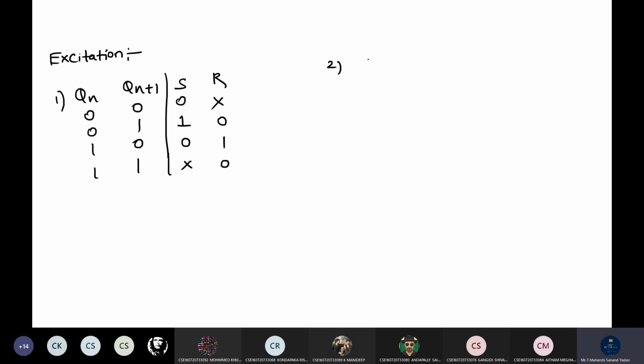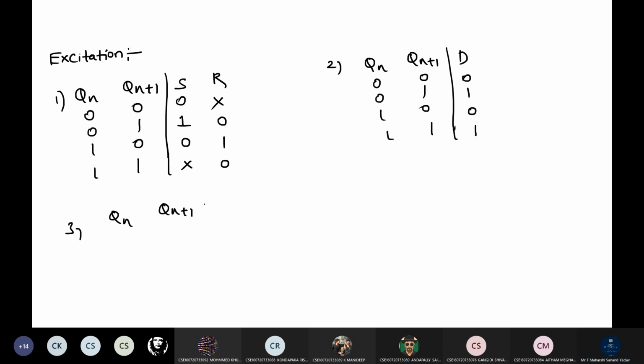Next, tell me for the D flip-flop: 0 1 0 1. Why? Because Qn plus 1 is equal to D. Next, third one, tell me for JK.